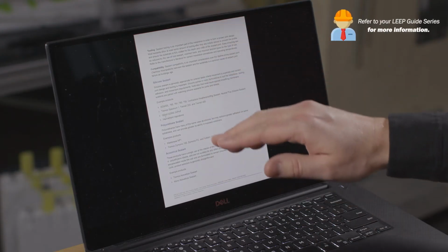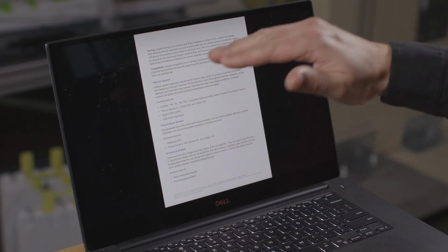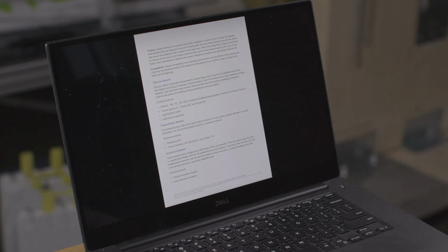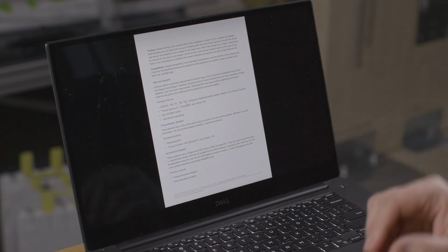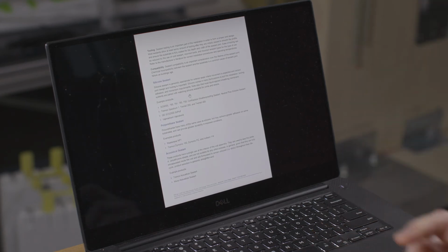With sealants, it's critical to properly apply them per the manufacturer's recommendations for surface prep, then tool the sealant. Proper application of the sealant, and the direction that you're applying the sealant, is also critical, and of course the compatibility. There are a number of different types of sealants. We've got silicone sealants, polyurethane sealants, and acoustical sealants, so some starting points here, and there's a whole number of different products. Silicone sealants tend to have the longest service life. They tend to last the longest out of any sealants, just because of the chemistry. And so silicone sealants are typically used in exterior applications.